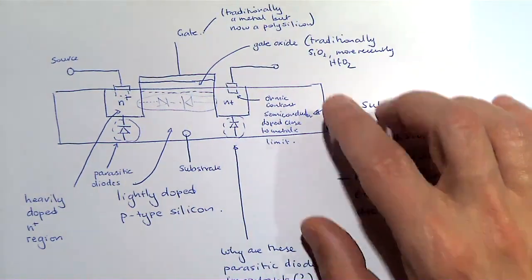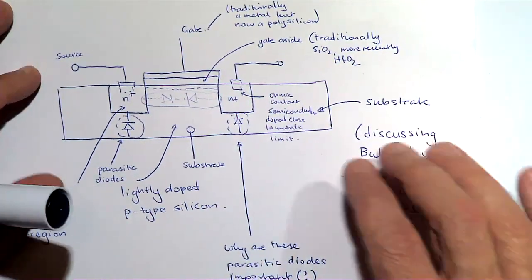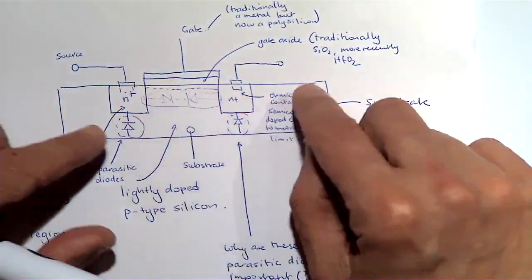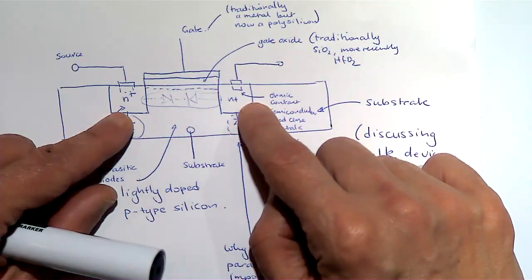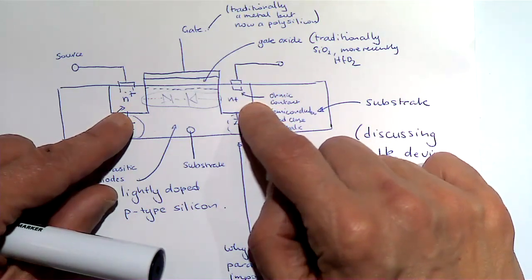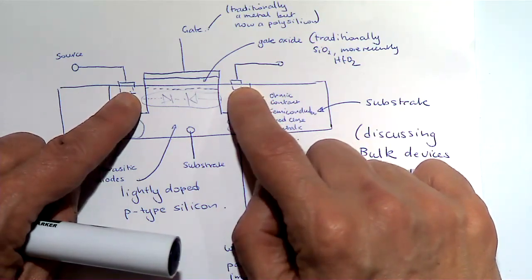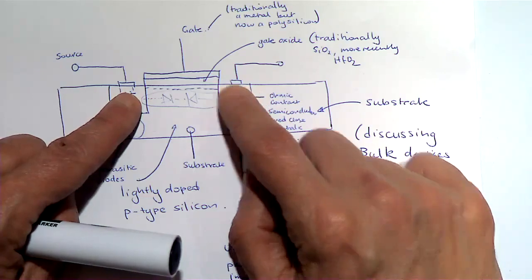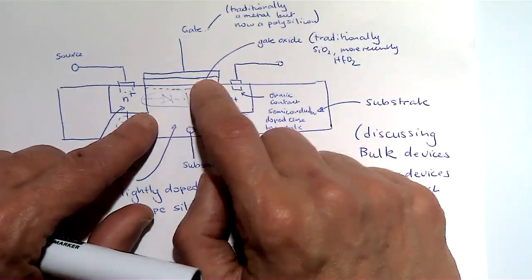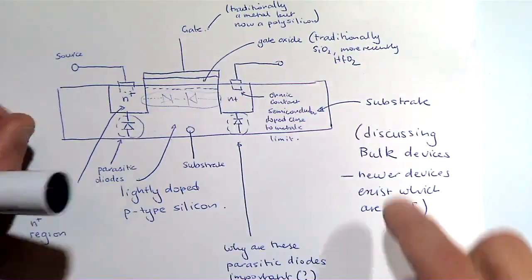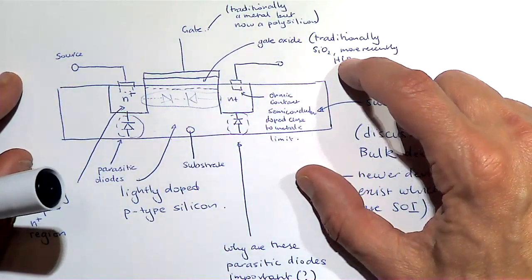All right, so essentially, this is the structure of the transistor, right? Just to reiterate, we've got the wafer, we've created two tubs, which are of the N-type. We're talking about an N-type transistor. And in order to make ohmic contacts, we've added another region which is very highly doped. We put the metal on there so that we can form ohmic contacts. And essentially what we've got is the oxide and the gate. And this is your MOSFET. You're an NMOS MOSFET.